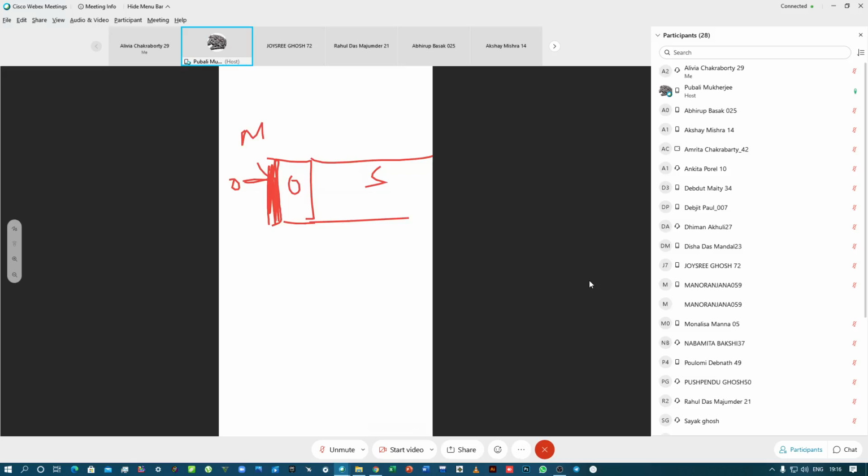Okay, and this is the gate terminal, if you're giving very, very large value of positive potential over here, so what is going to happen, there will be large number of negative charges accumulating. And remember we said when we were discussing the MOSFET actually, this very high value of negative charge required just for the conduction of drain current to take place is called the threshold voltage. So from this MOS energy band structure, we are trying to define such a condition.